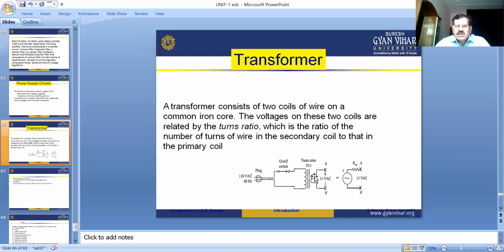It means two terminals of two diodes are connected to the positive terminal of the transformer, and the remaining two terminals of two diodes are connected to the negative terminal of the transformer. So two diodes are in forward condition and the remaining two diodes are in reverse condition. When two diodes are in forward condition, it means they are conducting at one time, and the remaining two diodes are off because of the reverse biasing condition.